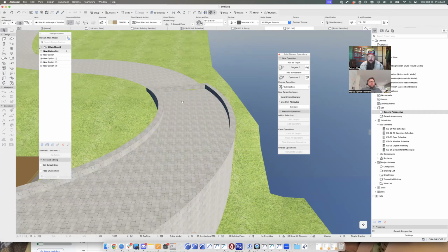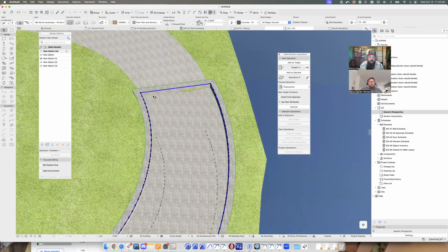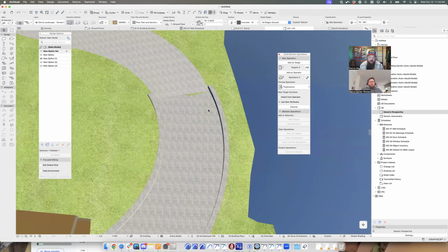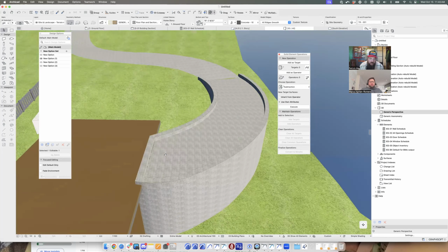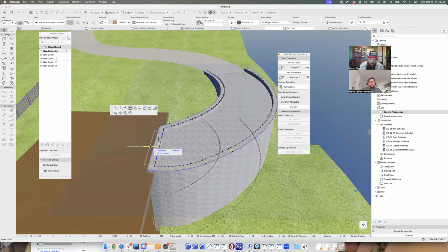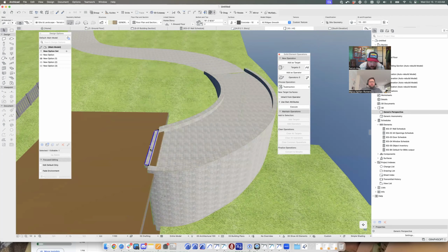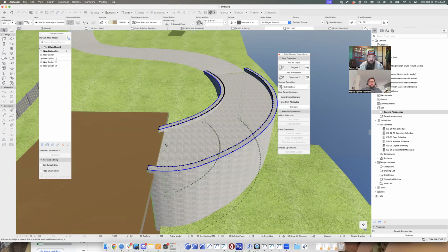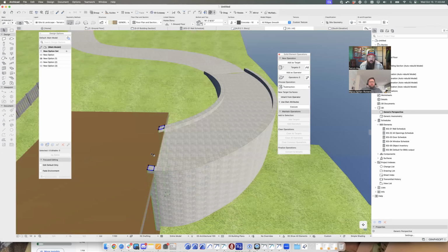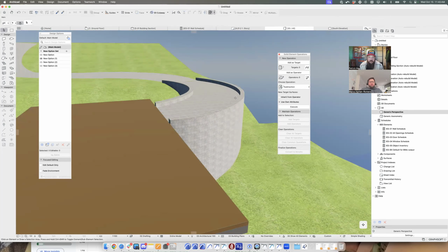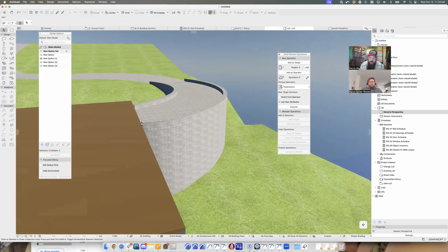Then I get that curb. I can keep tinkering away with it. Obviously, I don't need a curb that comes there, so we'll pull that part out. Don't need a curb here. We'll pull that part out. I decided I was going to add a node there. I can use the split command and split to that point right there, so I can get that curb around that driveway.